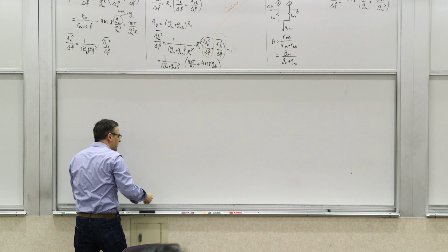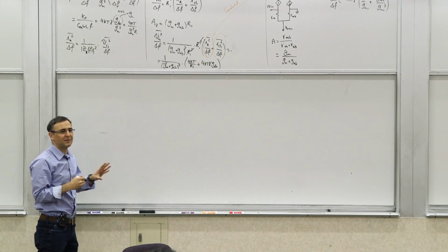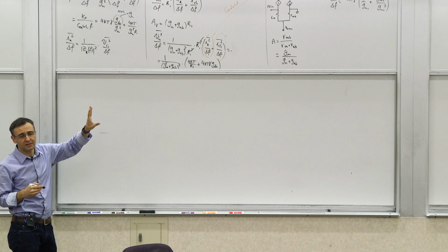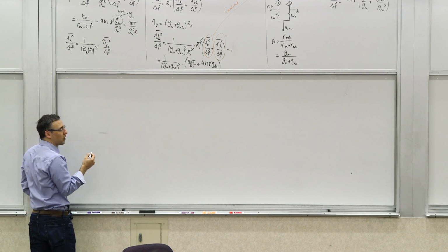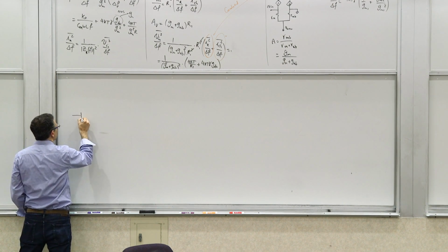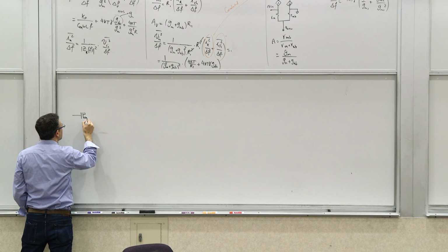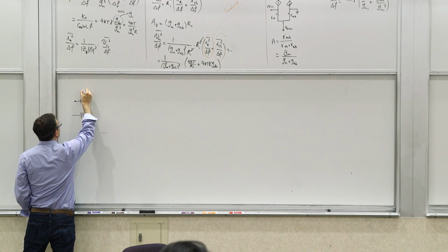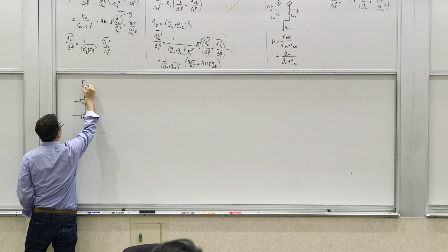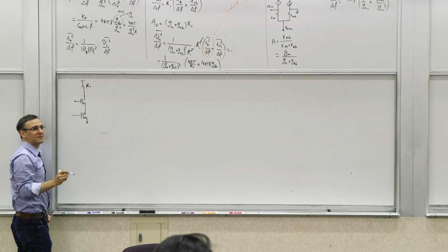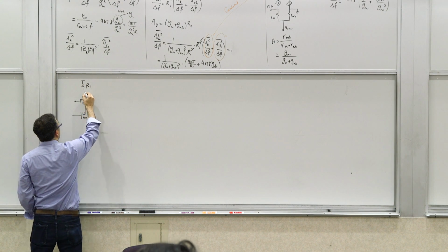Okay, so we talked about our 3 basic stages, right? The common emitter, common source, common drain, common gate. These are the stages we see frequently. Now, how about a cascade? What happens in a cascade? Now, we will start talking about noise and try to transfer the noise from one source from one location to another a little bit more implicitly, as opposed to explicitly always taking it to the output and bringing it back to the input.